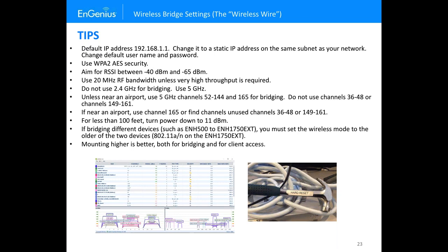Actually, it's slightly better. I don't know if you know this, but if you look at our MCS rates at maximum power, and this is true with any manufacturer, your MCS rates actually go down a little bit. At 26 dBm, your MCS rates are not at the top MCS rate. It's only at 22 or 21 or so, or even less. So it's a misnomer that you're going to turn up the power. Now at further distances, yes, sure, but at shorter distances, turning down the power is good.